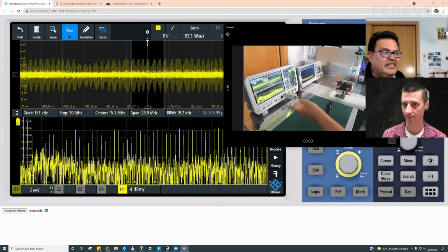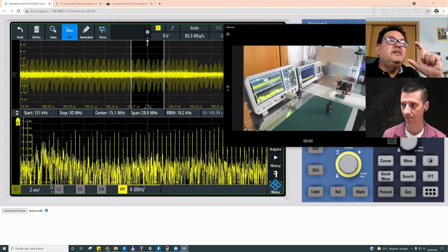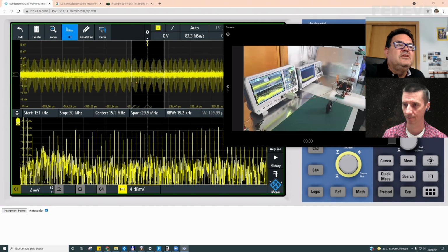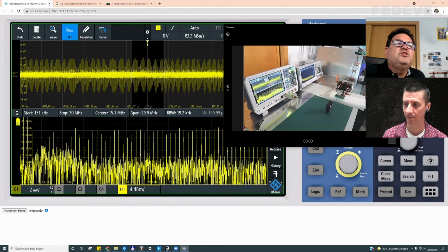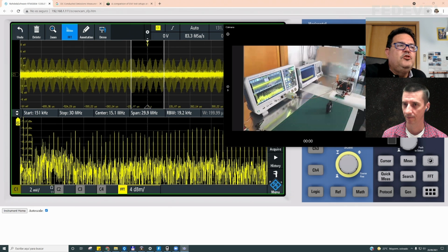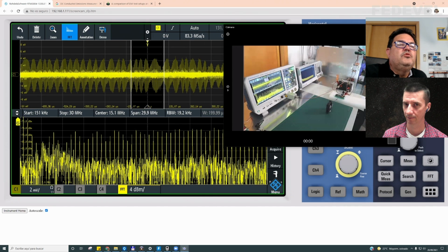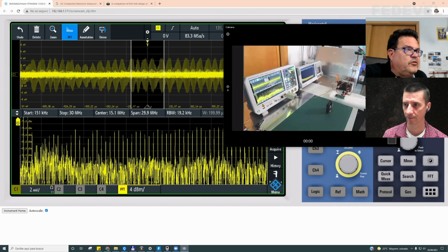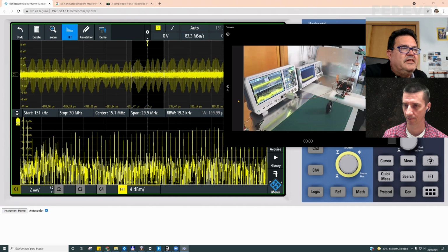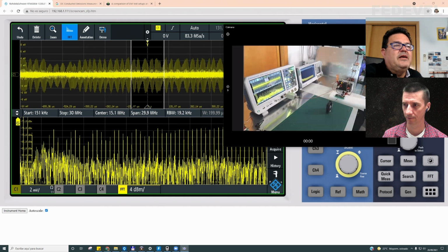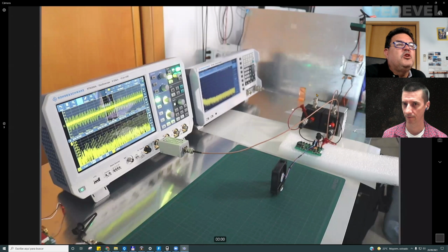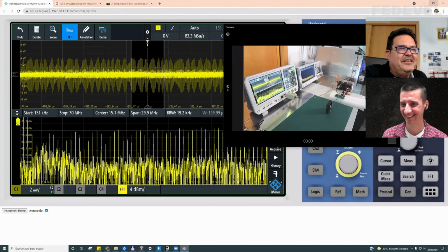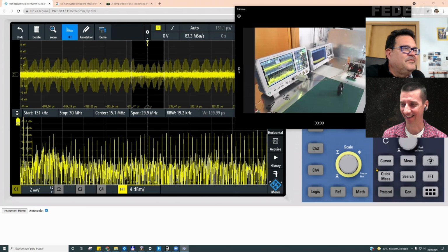So now the signal I am measuring is smaller in size, but at the same time, I am introducing the same frequency response. Usually when I am working with the oscilloscope, I don't use the transient protector, but for debugging purposes it's basically the same. But you need to check these kinds of things. Sometimes you can forget to put the 50 ohms termination, and you do a lot of measurements, and at the end you discover that the termination was not in place. So you need to repeat the test. These kinds of things can happen.